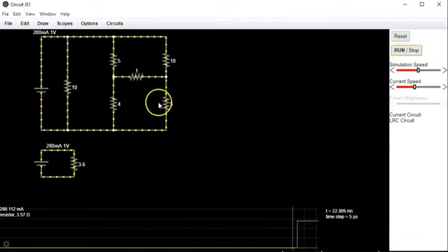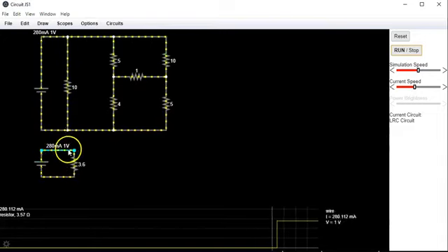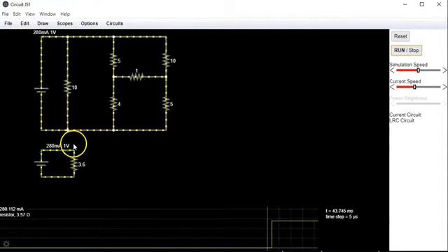As you can see, for a 1 volt DC signal applied to the terminals of the equivalent resistor as well as the original network, for 1 volt we have 280 milliamps, and similarly for the equivalent one we see 280 milliamps for the 1 volt. So that verifies that our operations have been performed correctly, and the theorems hold.